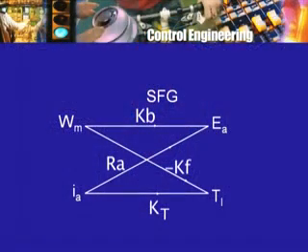What about the armature current IA, which is an input signal in this diagram? Well, it is not really an output in the sense one is not directly interested in the armature current per se, but it is not an input either in the sense you are not putting into the armature some current, rather we think of applying to the armature some voltage. So although this signal flow graph is correct, it is not a good one in the sense that it does not enable one to think of inputs and outputs the way we would like to.